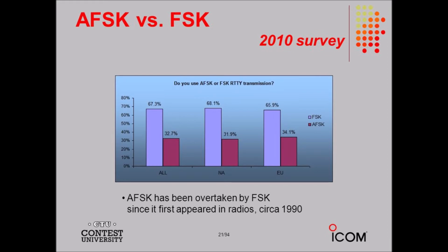In AM, at 100% modulation, the carrier wave consumes 2/3 of the signal power, and the sidebands exist as mirror image duplicates that, combined, employ only 1/3 of the signal power. These properties make AM inefficient and needlessly redundant.